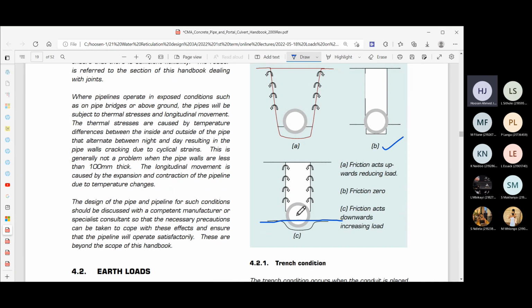So under these circumstances, what would happen is the soil directly above the pipe would carry that load. It would resist. It has to carry that weight of the prism above. But then, the soil that's adjacent to that prism over here, this soil here, can settle because the ground over here is not rigid. Right, so there'll be a settlement that will be taking place like that. So this is an embankment right through. So this soil all around here can in time settle down as it compacts like that.